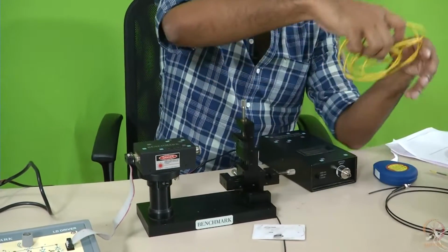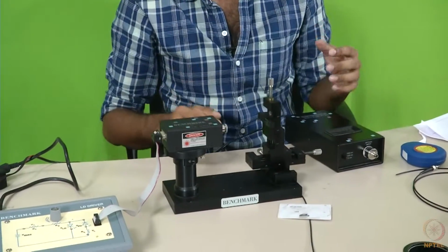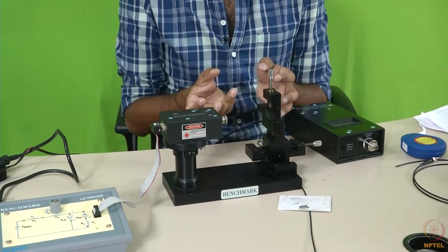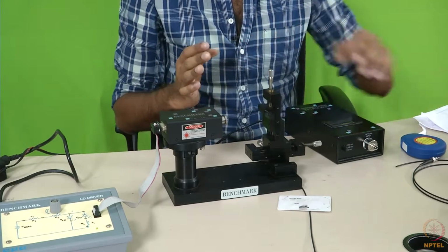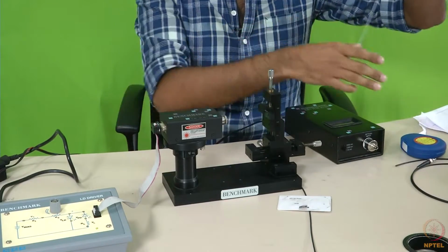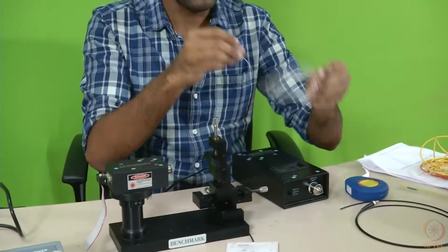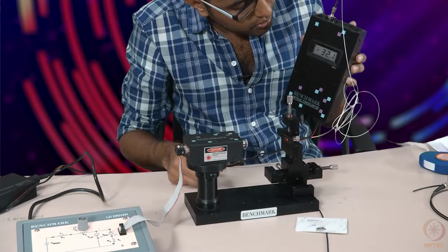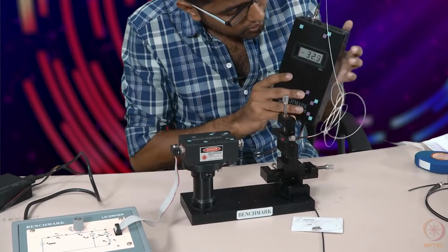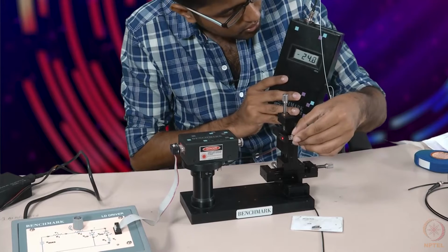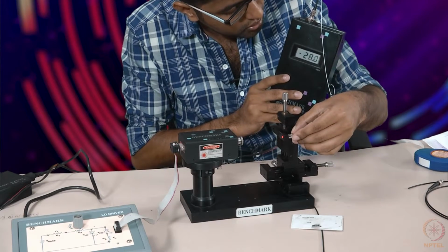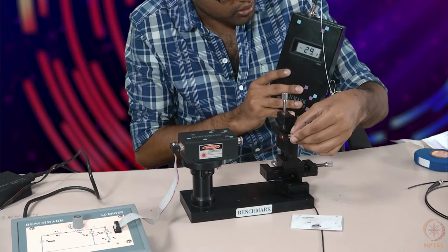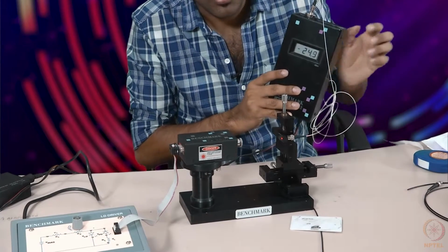But now we have something working in our favor, which is that we have already set up this XYZ translation stage on the lenses such that a rough alignment is there. So we'll see, just by plugging in the single mode optical fiber here, how much power we are able to get. Yeah, we are able to couple minus 32 dB, minus 27, 28, 29, around minus 20-something dB roughly.